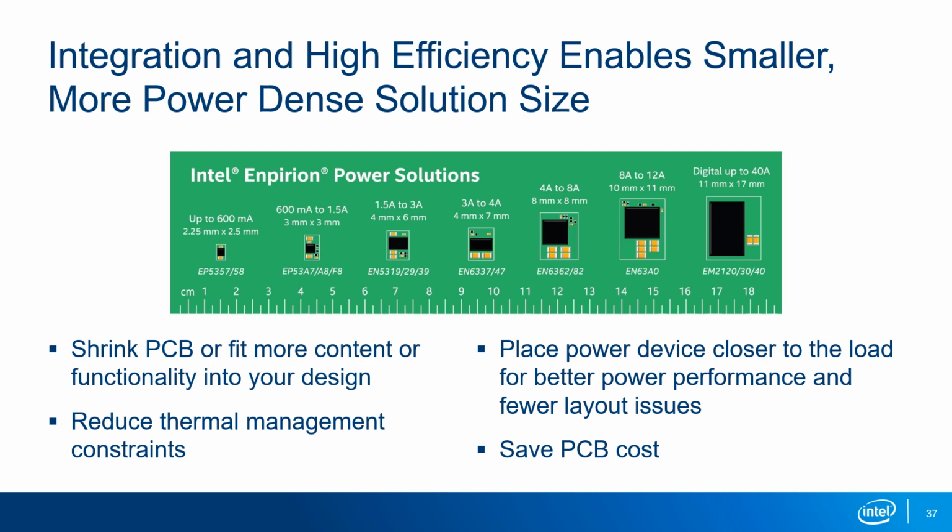For this integrated solution, you'll need a couple of input caps, a couple of output caps, and maybe 2 resistors. Again, it's very simple. It's as easy as designing an LDO, but you get all the benefits of a switch mode power supply. Here's a visual of the complete solution. No other components are necessary to operate with our integrated modules. Again, it's very simple, very straightforward.